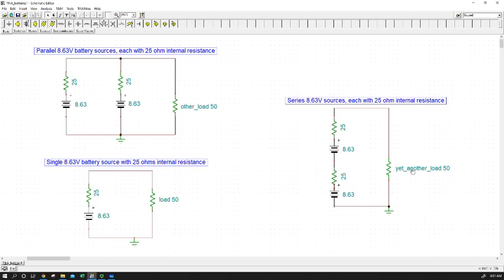So if you're looking at designing something where you have to supply a certain amount of current and energy is important, which it's becoming more so for any circuit, it's definitely worth doing what you can and what you can afford in your design to lower this internal resistance, because over a long time running a circuit, the cost of your energy is going to be significantly less the better the voltage source that you can operate with. So that's it for voltage sources, real and perfect, and hopefully it gives you a basis for your designs in both electronics and power supply.